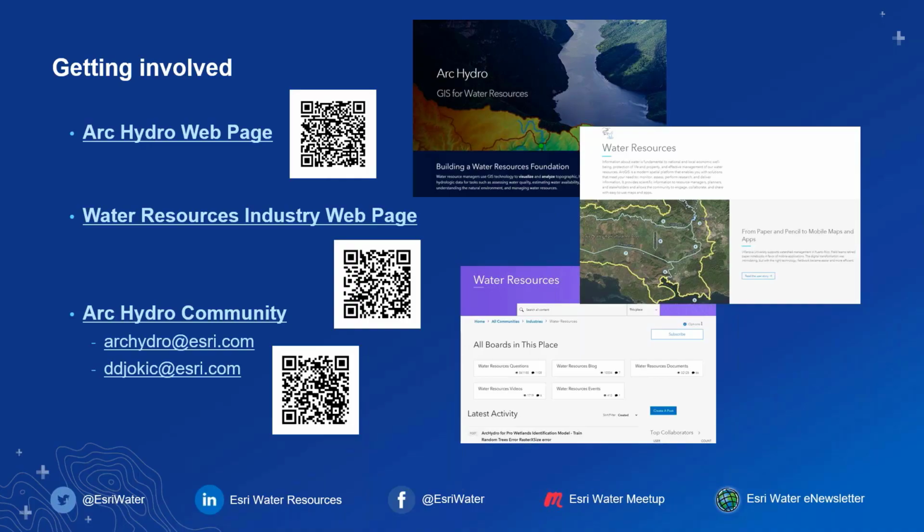We have a time lag, and so you can set up 2 identical basins. First one, you run the first storm through. The second one, you may put a delay in there of 24 hours or 48 hours, and then run the second basin through, and then both of those will be combined at the node. So there are several ways.